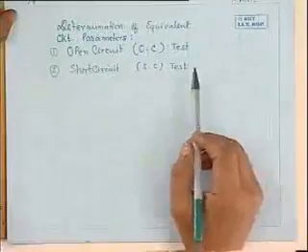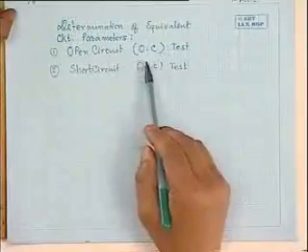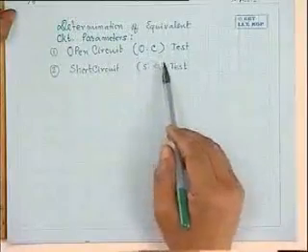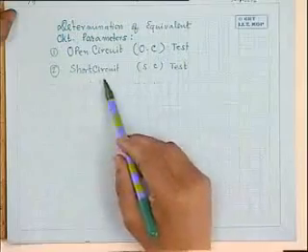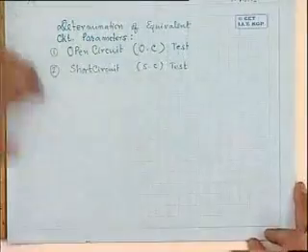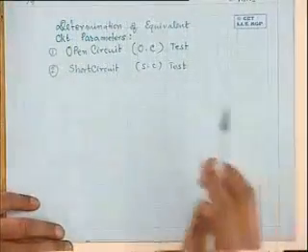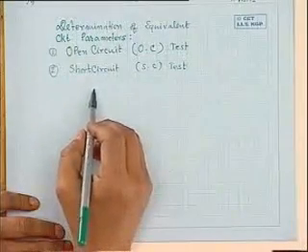So today we will try to see how the equivalent circuit parameters of a transformer can be determined by doing two simple tests. One test is called open circuit test, and in short it is referred to as OC test, and similarly there is another simple test called short circuit test or SC test. Now how these parameters can be determined, you proceed like this,